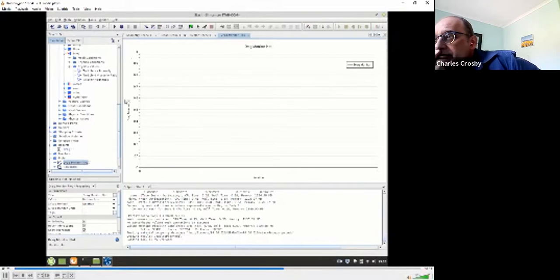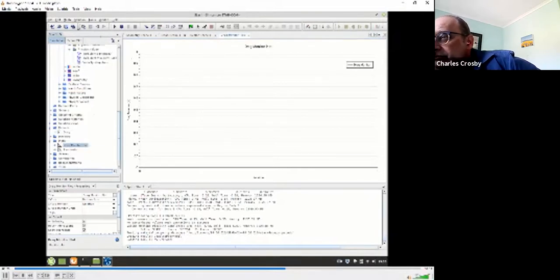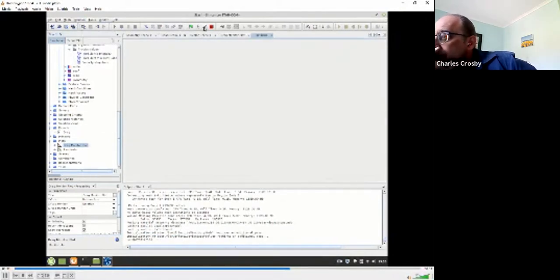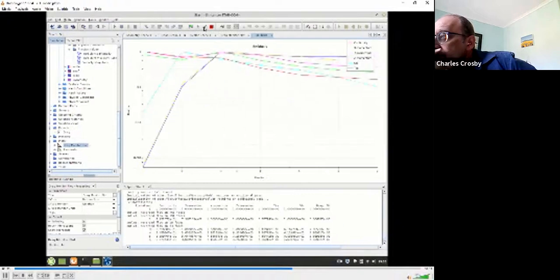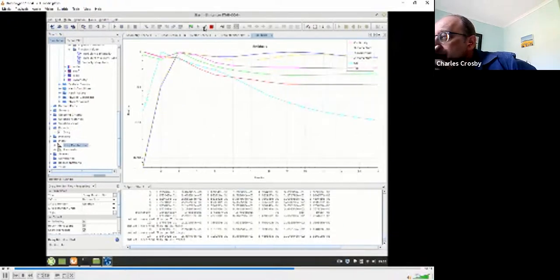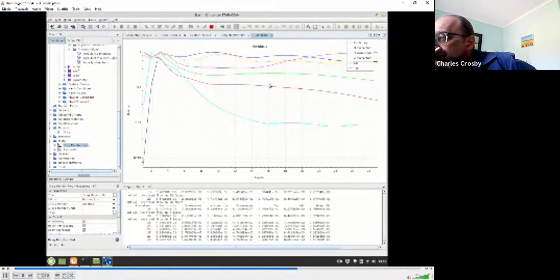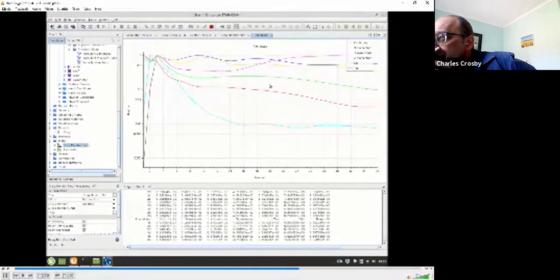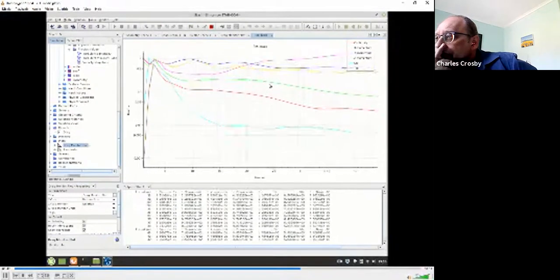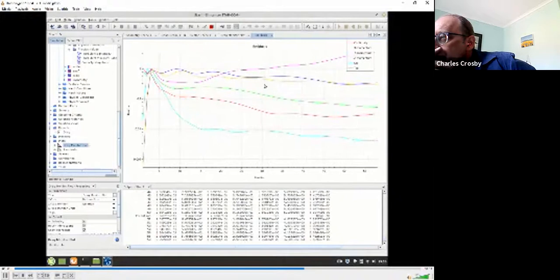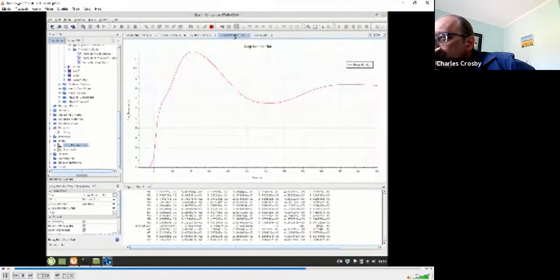So we're just about ready to do the run. We need to initialize the solution, and then we can hit the run button. And away it goes. There are a lot of parameters that you can set for the solution, but now we're just dealing with the simplest ones. It started off with a little bit of reversed flow at the outlet boundary condition, which is not necessarily a disaster. We can take a look at our drag.